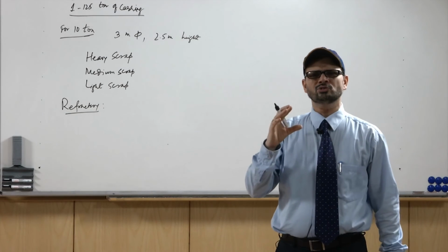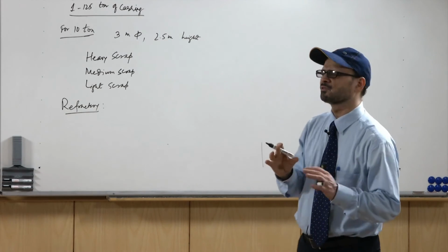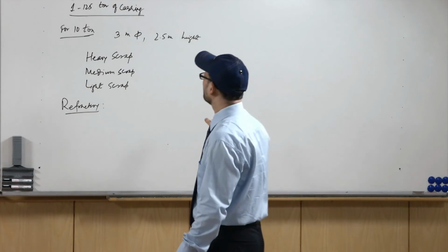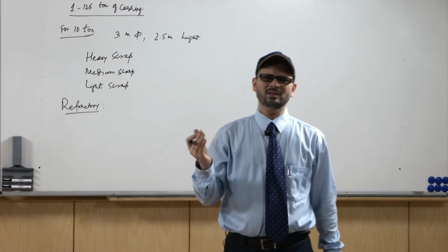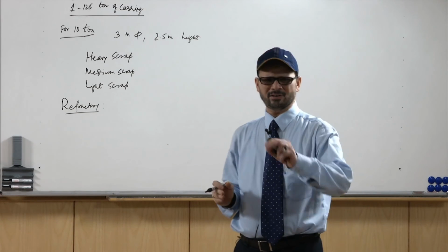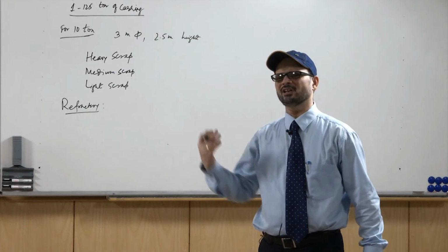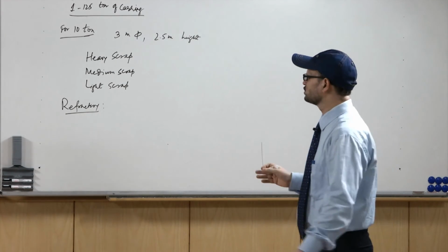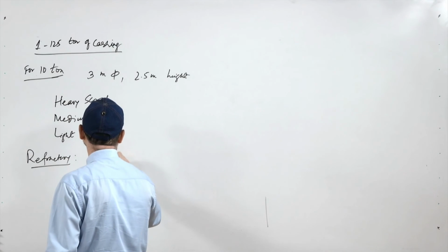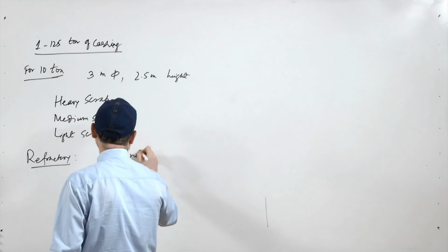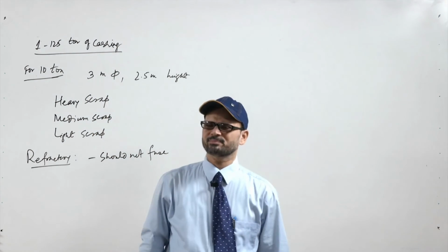They do not fuse below 1500 degree centigrade normally; that is the minimum requirement of a refractory, because most of the melting takes place below 1500 in non-ferrous and even for iron castings, but once we go for steel it is even higher. So, you need a material which should not fuse at the elevated temperature where the melting takes place.